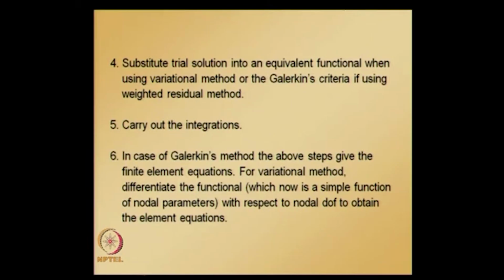So in today's lecture we will be looking at the Lagrange interpolation formula for constructing finite element trial solutions, that is, shape functions for second order boundary value problems, and also the basic concept of isoparametric mapping, where shape functions are used for transforming the physical element geometry into a simple parent element geometry. A quadratic element for a general one dimensional boundary value problem is going to be presented, and we will be developing finite element equations using the quadratic element for a general one dimensional boundary value problem using the Galerkin method.